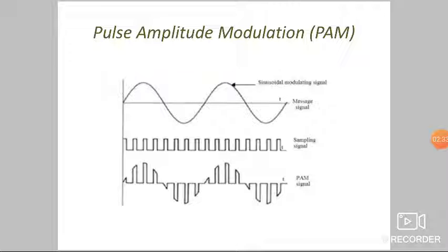Here a signal which is sampled at Nyquist rate can be reconstructed by passing it through an efficient low-pass filter with exact cutoff frequency. It is very easy to generate and demodulate pulse amplitude modulation. This technique transmits the data by encoding the amplitude of a series of signal pulses.